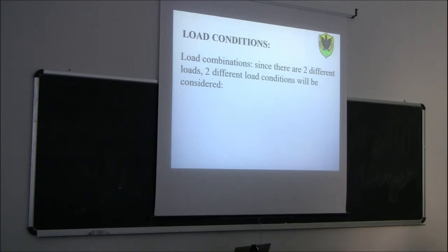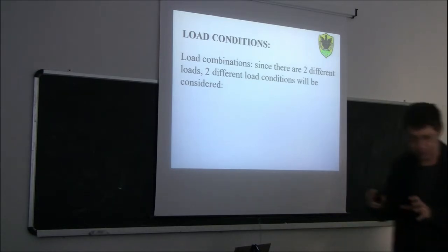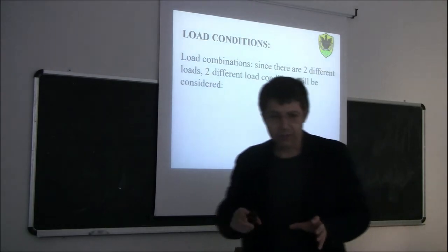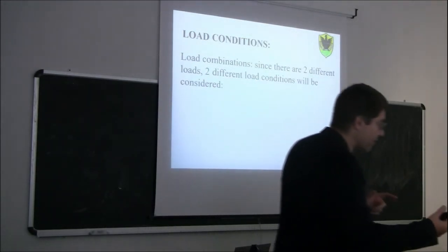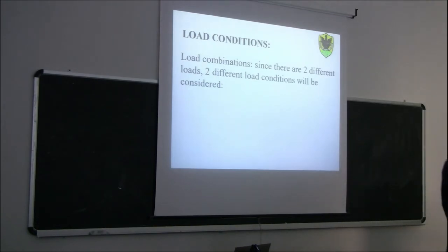Clear? Okay, since now we are talking about timber, I told you that if we have different loads in the same load condition, the strength also depends on the load condition, because the strength depends on the load duration class via the K mod factor.